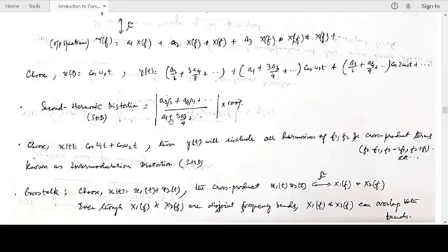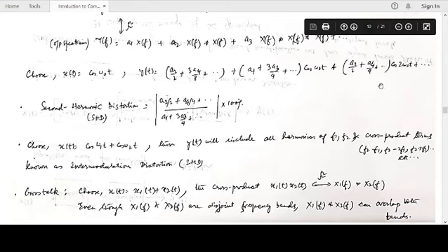So in a nonlinear system, these are the parameters of interest. Similarly, there is third harmonic distortion. Let's say you somehow suppress the second harmonic by using certain techniques, then you need to go to the next higher level, which is THD, third harmonic distortion. We talked of balanced and unbalanced transmission lines. If you have a balanced amplifier or balanced filter, you can somehow suppress the second harmonic, but then the third harmonic comes into the picture.